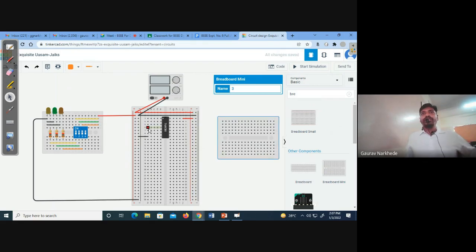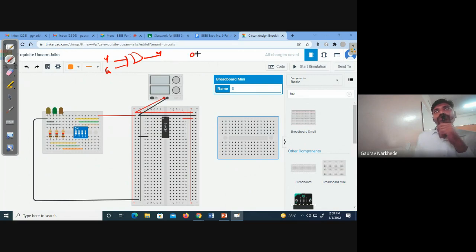So look, the gate inside here is which gate? It is an XOR gate. So let me just draw it here, and let me tell you that your XOR gate is like this, right? Let us say this yellow and green are your inputs, and let us say Y is your output, okay. So its possible combinations are 0 0, 0 1, 1 0 and 1 1, right? So what is the output of the XOR gate? Output of XOR gate is 0 1 1 0, right? So this table we need to verify.